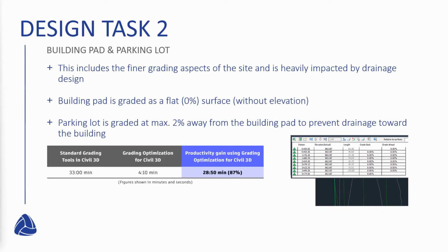And what then happens is after this process, this iterative process is run and it obtains its final design, your polylines would then be converted into feature lines. So basically looking at this would be your building pad feature line. It would have been applied now in elevation. All of the edges would be the same elevation. It would be at a 0% slope all around. So you can then just go and select all of these values and update it to an elevation which you feel comfortable with to test that out.